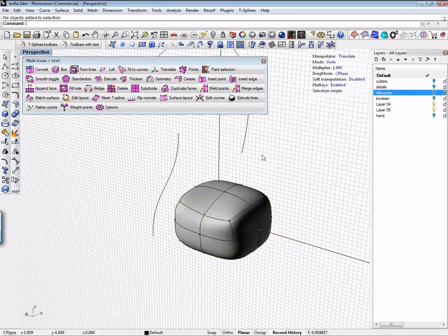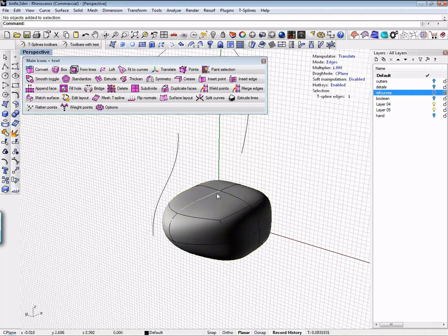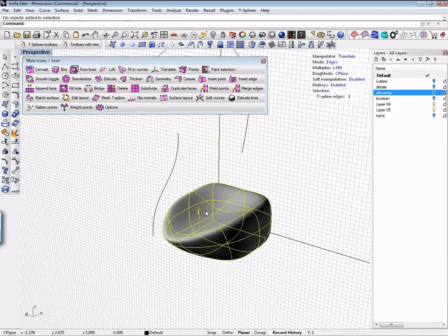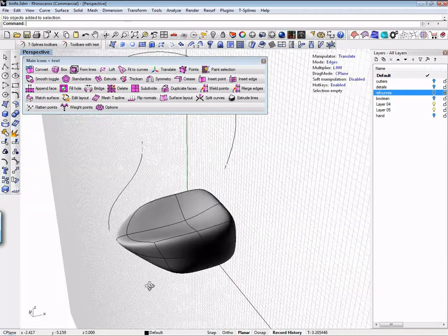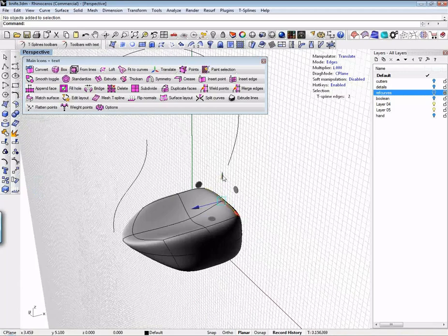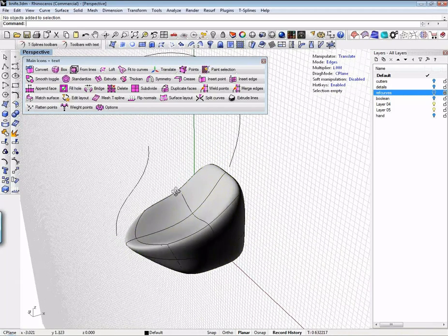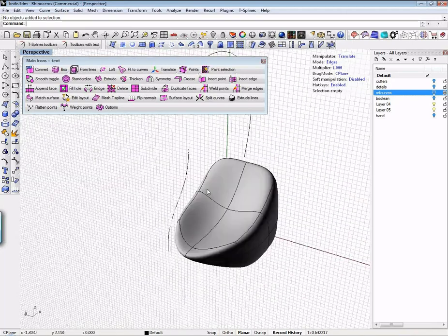level. So those are kind of the three components of a T-Splines object, and how you use those are going to determine how you add your detail and make your manipulations. But this is basically how you interact with a T-Splines object. You're going to make something, and you're going to either add or remove detail, and then you're going to kind of stretch and push and pull and sculpt it until you get something that you like. And you'll notice that the whole time it's maintaining this wonderful smooth transition from one bit and piece to another.